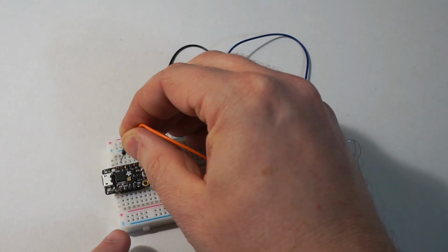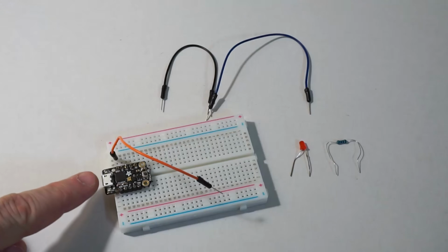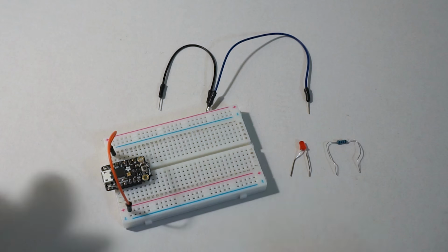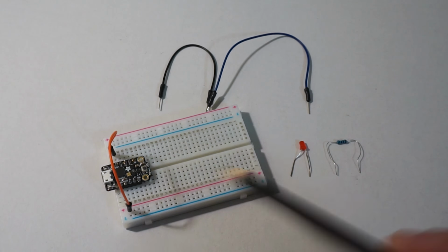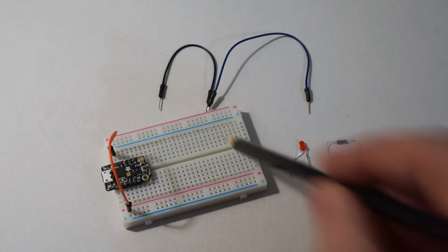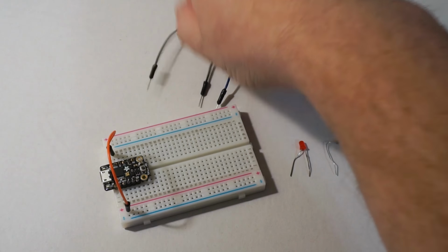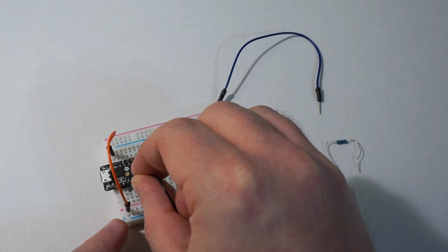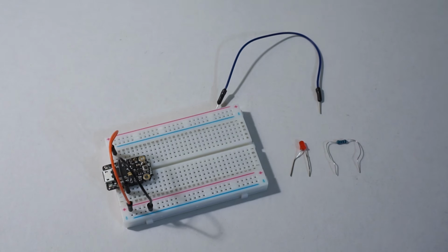And we're going to take it from this USB pin, which is the same as 5 volts that comes in through the USB, and we're going to connect it to the positive rail. So if you remember on these boards, this whole line here is going to be positive, this whole line here will be ground, and the pins are connected across the board like this. So that's why this one here is connected to this pin here. And we're going to do the same with ground. There's a ground pin here on the Trinket, which is this second pin in here, and we're just going to connect that up to the ground like that.